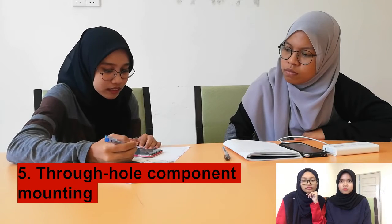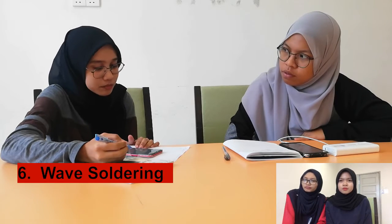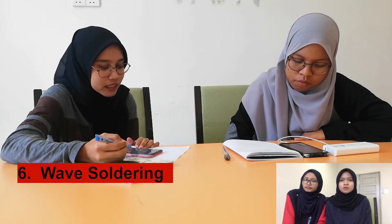The fourth step is rework. In rework, if any component connections are not secure, it may be necessary to solder them manually. The next step is through-hole component mounting. The through-hole components, if any, are mounted at this stage. The next step is wave soldering. It is performed if through-hole components are used.